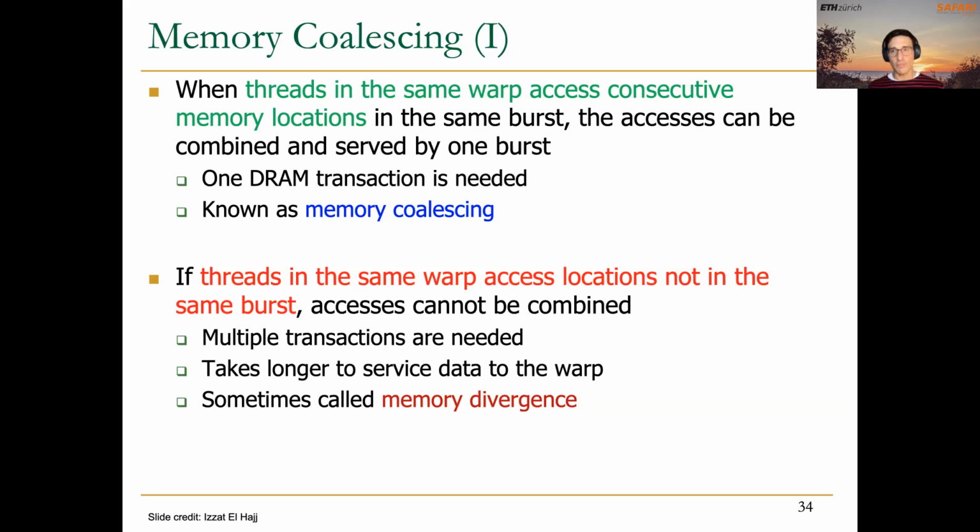Notice the difference here. If we go to memory with one whole warp, all 32 threads of the warp want to read data from memory, we open one row, we place this row in the local row buffer, and we start reading elements or cache lines from this local row buffer. All threads from the same warp access memory together, because they execute together as a SIMD unit.